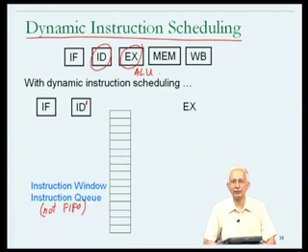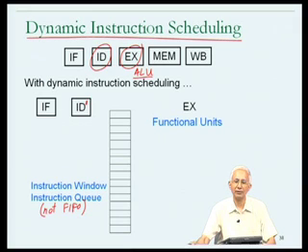However, we do know that even in our MIPS1 instruction set, there are instructions which cannot be executed by the ALU. For example, there could be floating point instructions. So we suspect that in addition to just the ALU, for the execution of instructions, there may be several pieces of hardware, each specialized to do different kinds of operations, and that therefore thinking about the processor pipeline as just having an ALU is not realistic. Rather, we should think of a pipeline which has many different pieces of hardware for different functional capabilities as far as the instruction set is concerned.